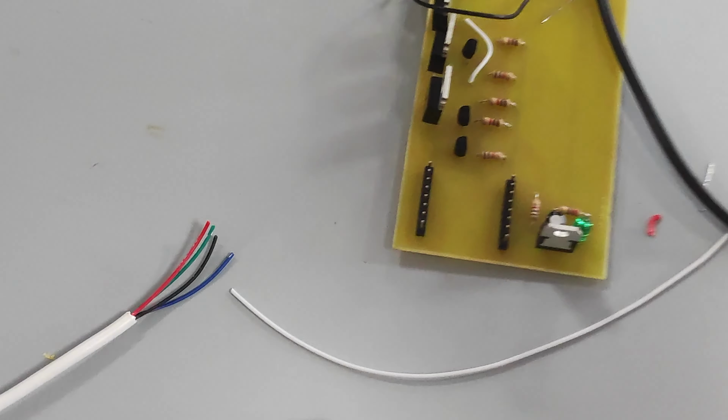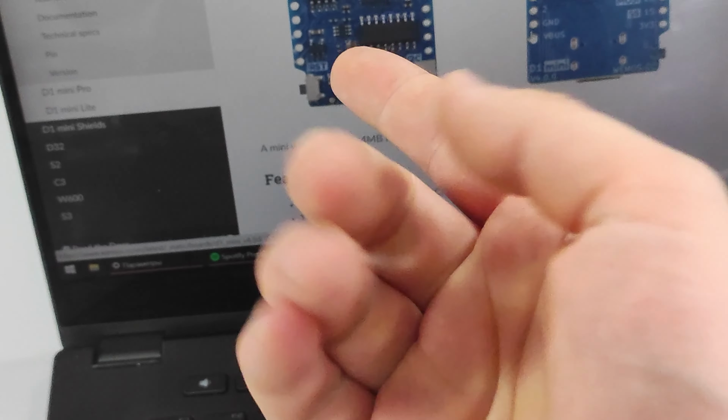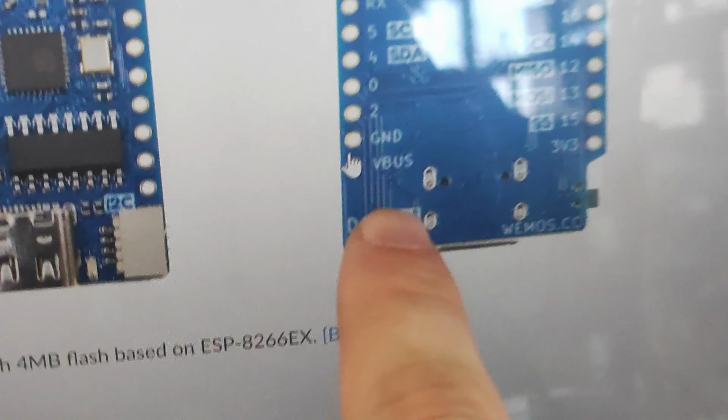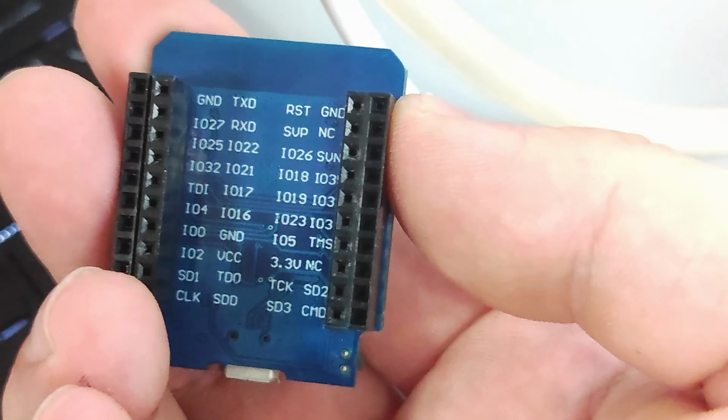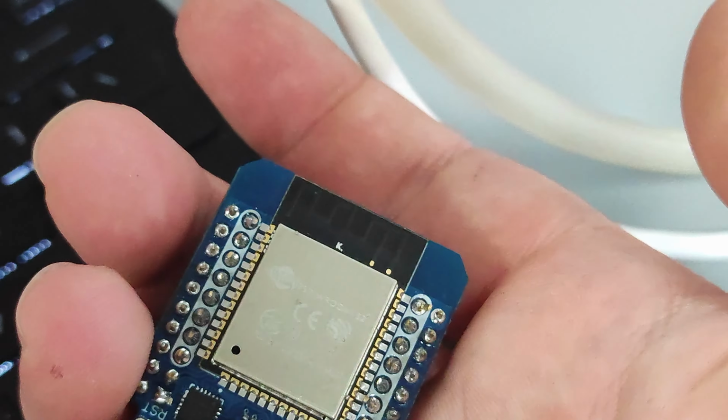A very fun detail I figured out on the PCB board that I made for prototype 1. As you can see, there's official documentation for this board. And as you can see, the last pin is power in the documentation. However, on the actual board, it's not. The lesson learned: always check footprints before making the boards.